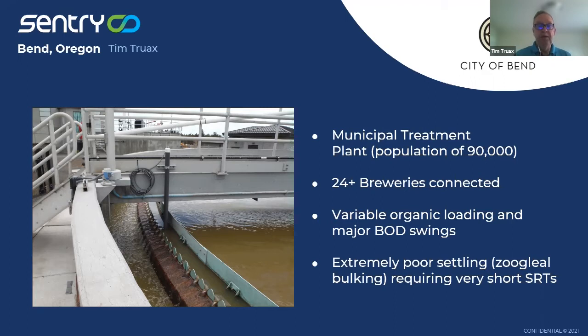Now, the plant is a 4-stage Bardenpho process. The aeration zone is IFAS, integrated fixed film activated sludge. The permit limitation is 10 milligrams per liter of total nitrogen.